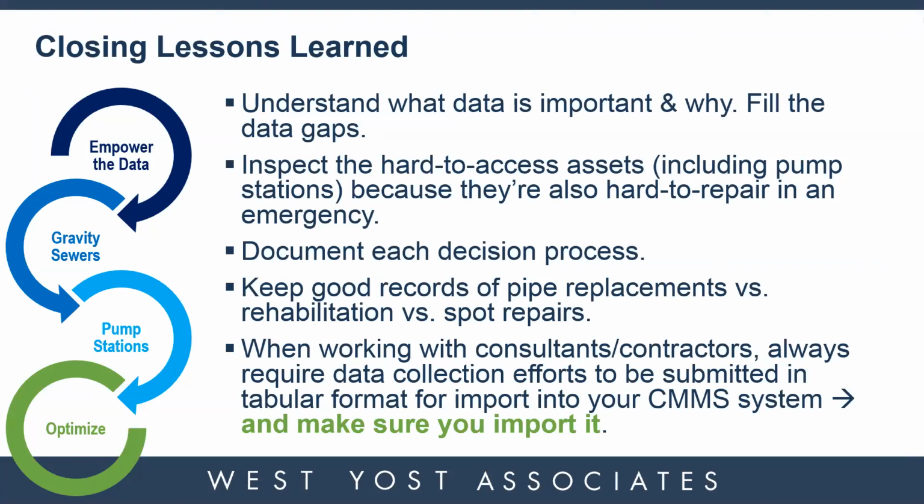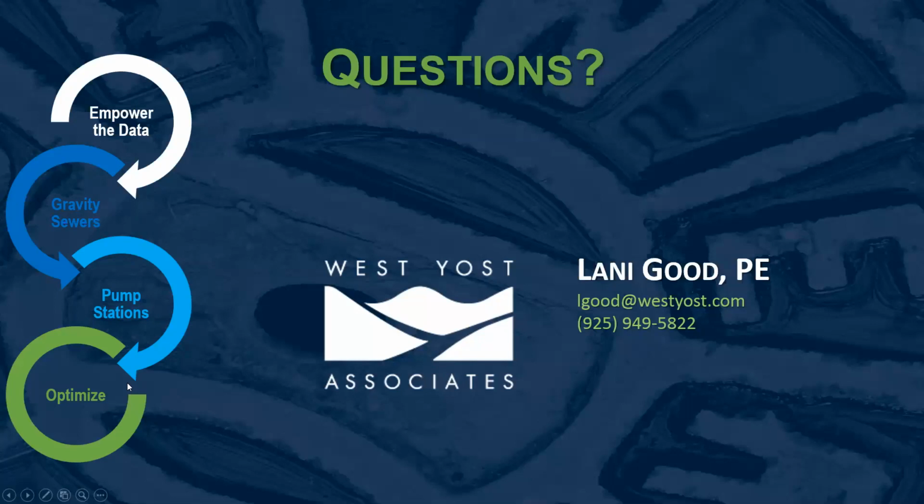And then finally, when working with consultants or contractors, like CCTV contractors or improvement contractors, always require the data collection efforts to be submitted in tabular format for import into your CMMS system. So if you have a consultant modifying your GIS, or CCTV contractors creating databases, make sure you get a big consolidated database at the end, and make sure you import it. Don't leave it on some other system or in your email. Make sure you import those. And with that, we'll open for questions.